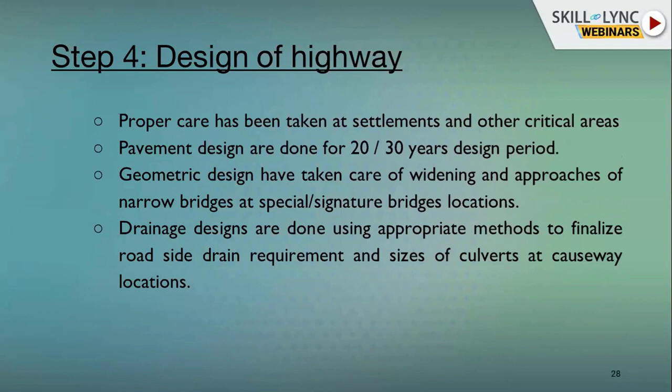Pavement design is to be done for 20 years or 30 years: 20 years for flexible pavement and 30 years for rigid pavement, meaning concrete pavements. Geometric design takes care of widening and approaches of narrow bridges and special or signature bridges. Here the role of the highway engineer and bridge engineer will be very important. They will decide the type of special signature bridge. Then comes drainage design, based on various methods: roadside drains, how much culvert size is required, what the drain requirement is, all those things will come.